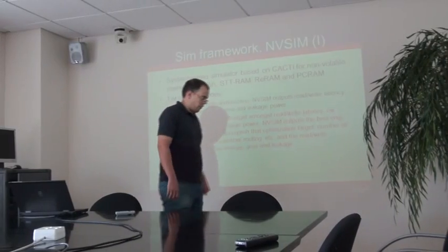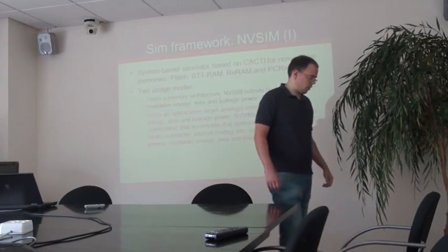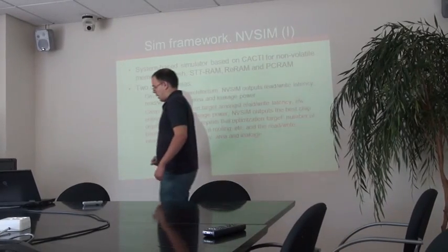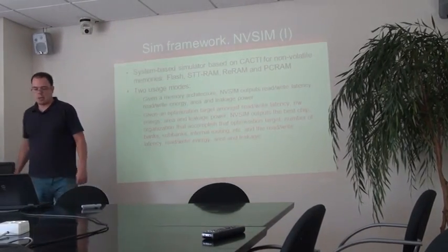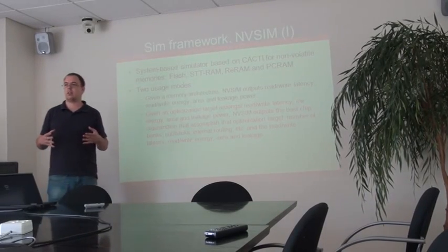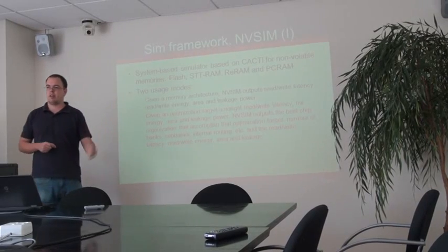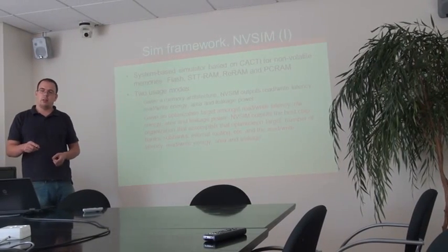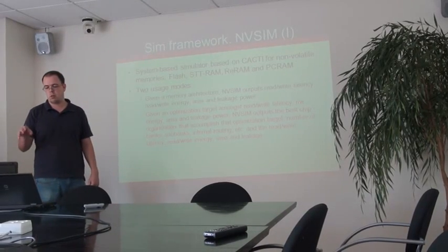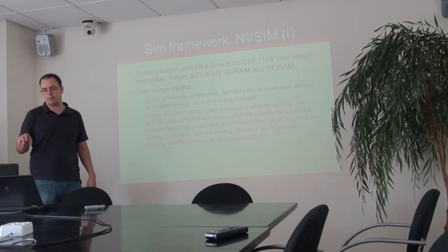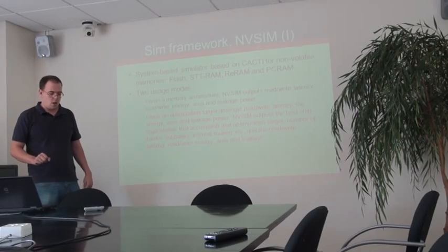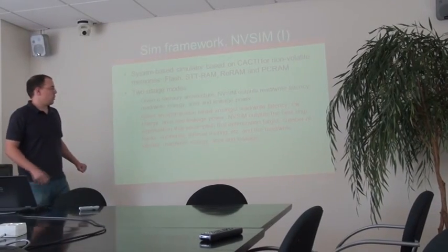I will continue with a description of the simulator. NVSim is a circuit-based simulator, and it has two modes of usage. Say that you have a chip, and you have in mind an architecture with the number of banks, the number of sub-banks, the internal routing and so on, and you want to estimate the power, the latencies and so on of your chip. So you put your chip specifications in the simulator and you get the resulting metrics. The other mode, in red, is the one I used.